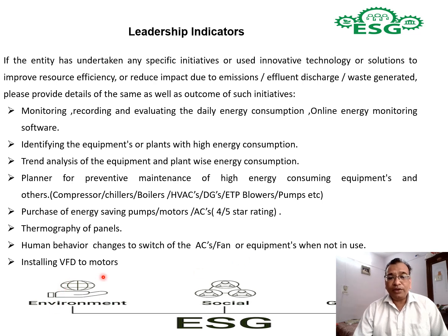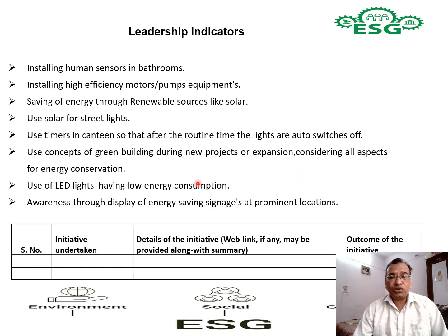Then installing VFD to motors. This is well known, and many industries adopt this. Variable frequency drives you have to install to the motors, and they will consume very less energy. Then you can install human sensors in bathrooms or washrooms. Wherever there is less manpower movement, usually in the second and night shift, in those areas the illumination will be controlled and power consumption will be reduced.